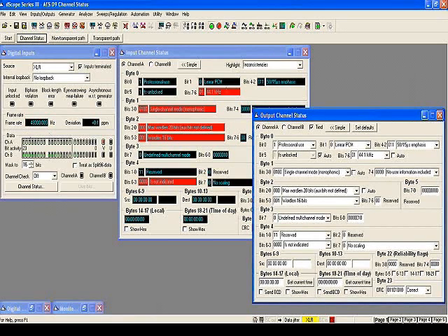It allows you to quickly identify this type of problem. When you have inconsistencies in the sample rate, depending on how the manufacturer implemented it, a piece of equipment may just mute. It may not pass audio. So if we're trying to analyze what's coming down from the last piece of equipment, this is the dialog box we're looking at.